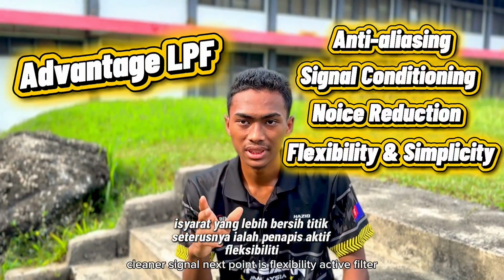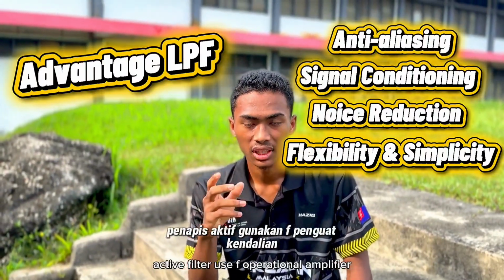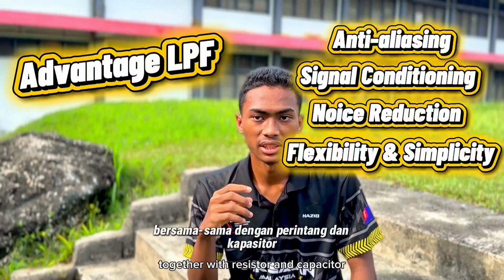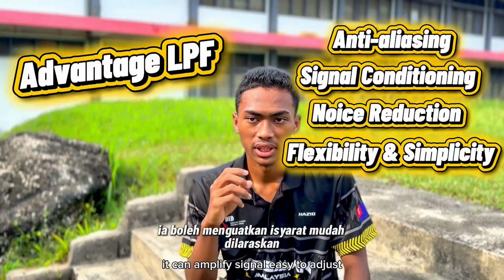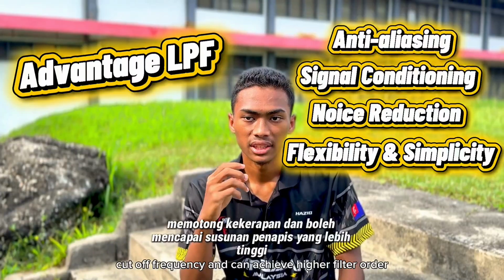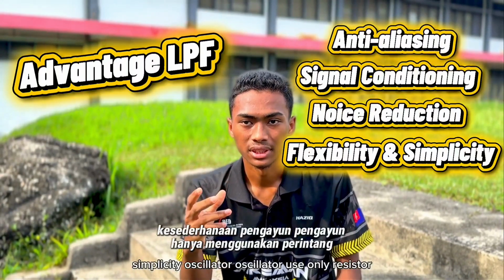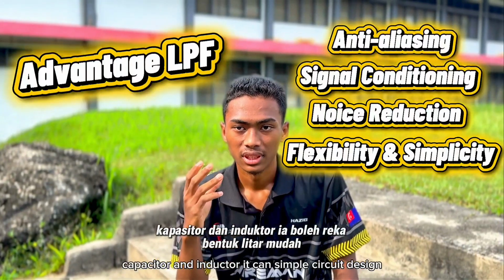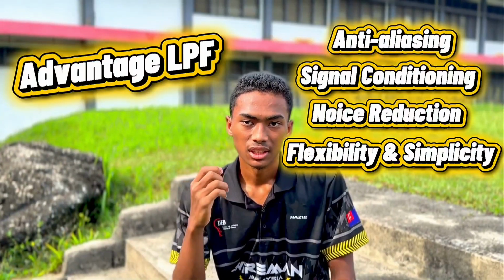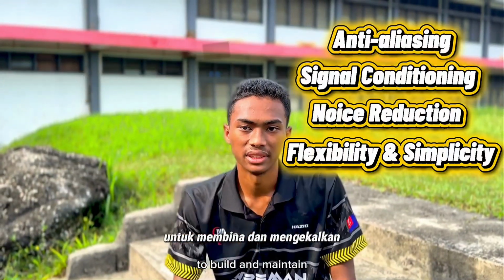Next point is flexibility, active filter. Active filters use an operational amplifier together with resistors and capacitors. They can amplify signals, are easy to adjust the cut-off frequency, and can achieve a higher filter order. Simplicity, passive filter. Passive filters use only resistors, capacitors and inductors. They have a simple circuit design, low cost, require no external power supply, and are easy to build and maintain.